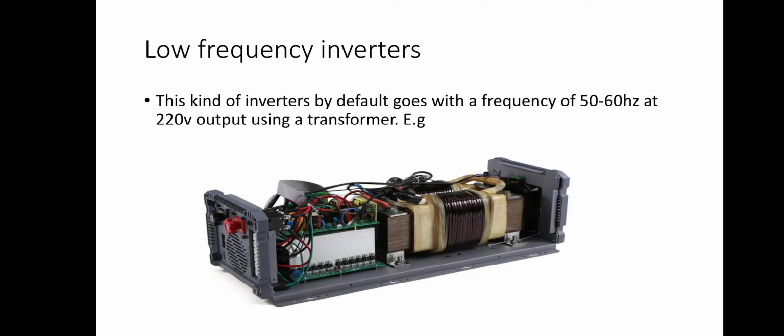So these are for low frequency inverters. Now the disadvantage of this low frequency inverter is the no load current. Most of the time you see the no load current very high. When there is no load attached to it, you notice the no load current is very high. That is the disadvantage of this low frequency inverter over the transformerless inverter. That is for transformer based inverters. That is the only disadvantage you will have on this system.